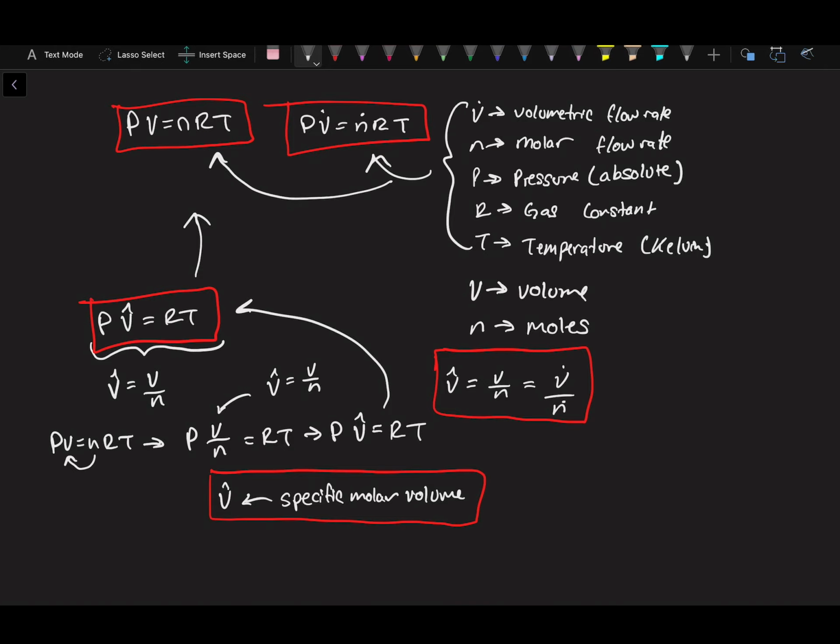If the gas is in low pressures, then you're in an okay spot. If you start getting high pressures and insane amounts of temperature changes, then you might have a non-ideal gas, and different equations would have to be used for those kinds of problems. But typically you're going to be told that the gas behaves ideally, and when you're told it behaves ideally, you should be thinking PV equals nRT or PV hat equals RT. Both equations are equivalent. It's just a matter of what information you're given in the problem and how you could plug it in to get your final answer.